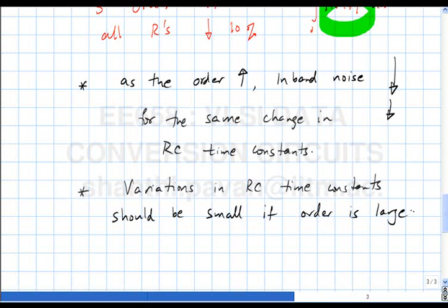I can't really say more. See, the Bode sensitivity integral is just giving you a rough idea of what happens out of band. It is not telling you what the exact shape is out of band. That will depend on the details of the NTF you started off with and how you vary the components. So at this point, the short answer is that it is not possible to comment on how much the maximum stable amplitude will change if the in-band gain reduces by some factor.